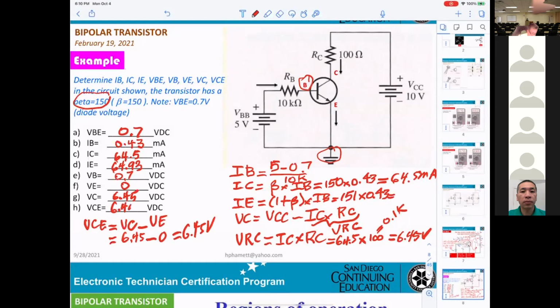Mr. Pham, I think VC is supposed to be 3.55. Oh, sorry, yes, I know. Okay, thank you. VC equals VCC minus VRC, and this is the VRC, not the VC. So you want the VC.